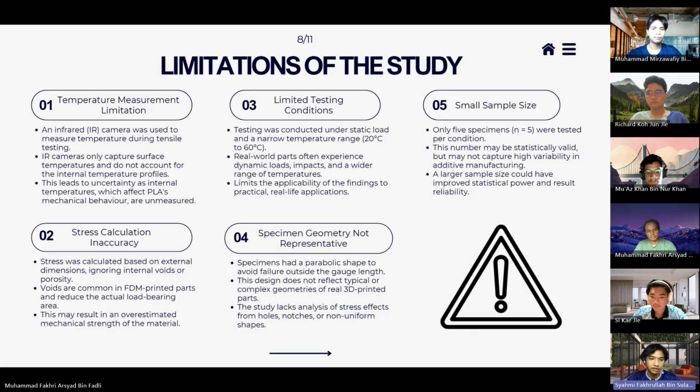Next, the stress calculation inaccuracy. The stress was calculated based on external dimensions that ignore the internal voids or porosity. Voids are common in FDM printed parts and reduce the actual load-bearing area. This may result in an overestimated mechanical strength of the material.